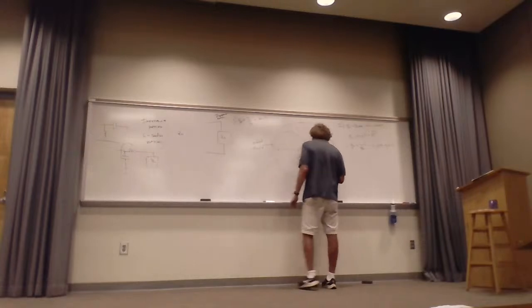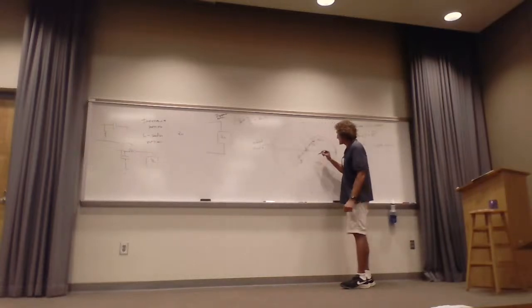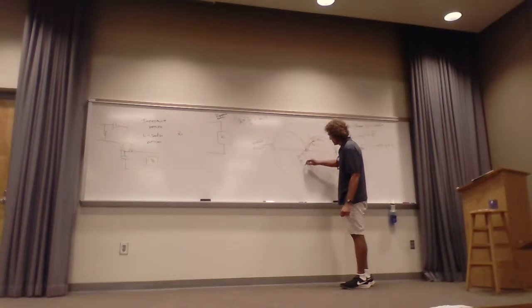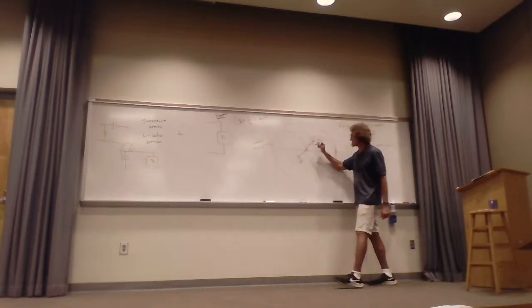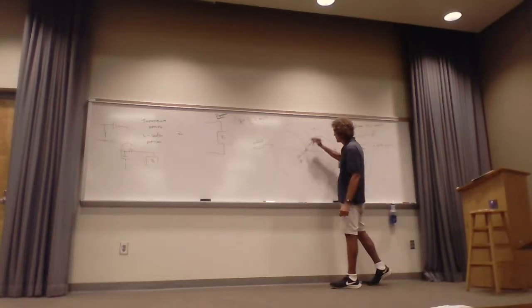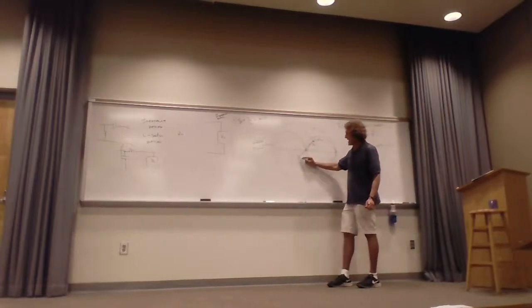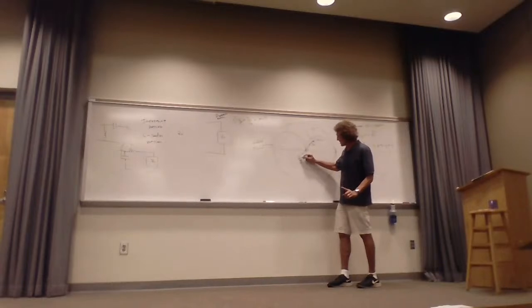Remember, if I'm adding admittance, I can get this thing, I'm trying to draw this here. This has a real part of 0.4, so y'all see I'm trying to show you this is the circle that would have 0.4 as the radial distance, right? Now look, I can add a plus or minus J something and hit that point, or hit that point. Y'all follow me?